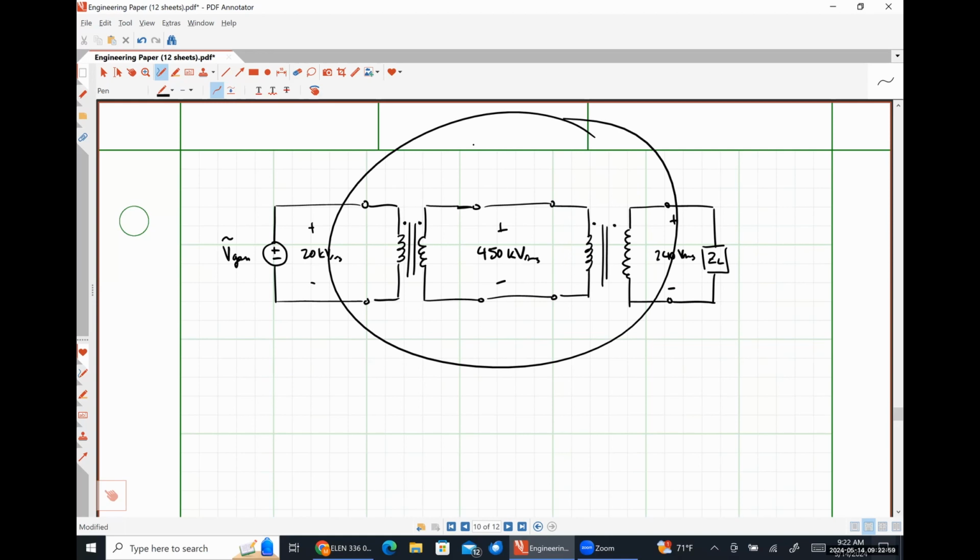If that switch were to fail, the other thing would be permanently disconnected because it's an either or situation, not a both. So you would always be running off of grid power or always be running off of generator power, but they're never intermingled. So nothing could accidentally go. Yes. The grid and the generator are never connected together.